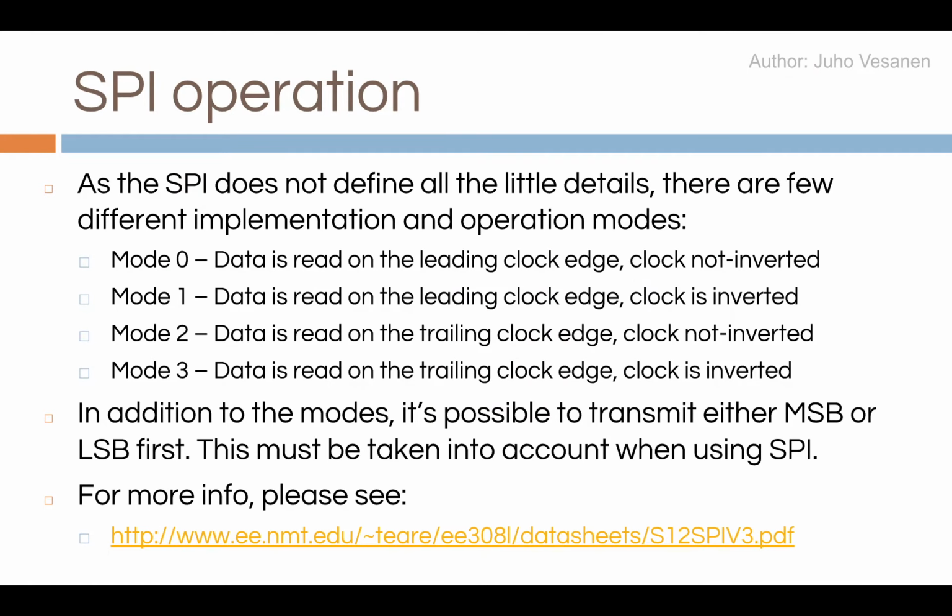Okay, since there is no definition for the data synchronization, basically there are 4 different operating modes. Either leading clock edge or trailing clock edge, and then if the clock is inverted or not inverted.